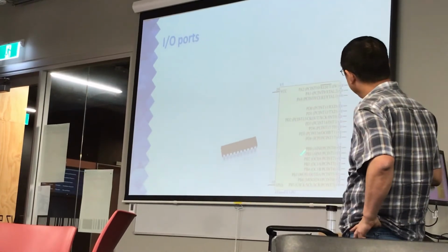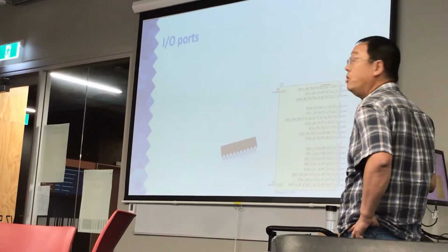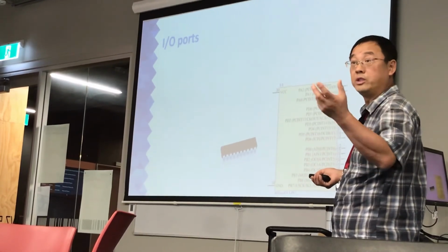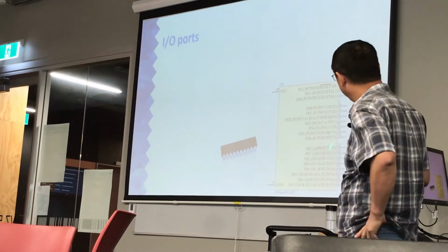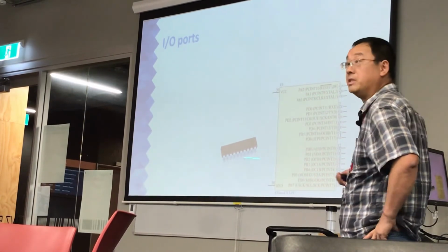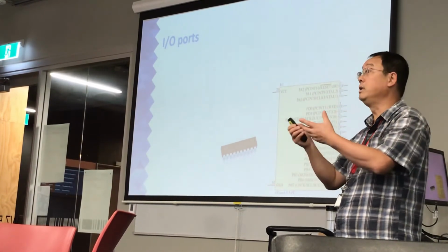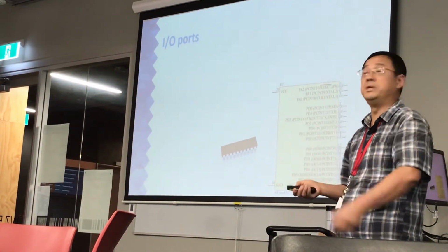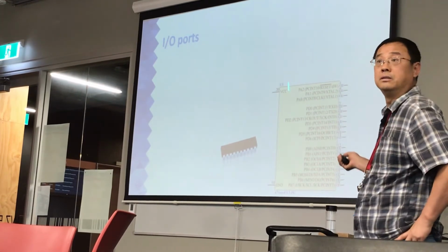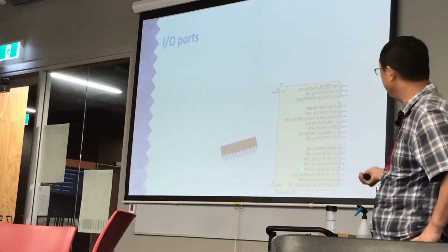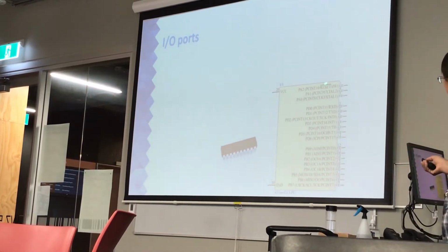For the microcontroller, we can see that one of the microcontrollers is the ATtiny4313, a little bit different from the 2313, which we use on project 2. The reason it's different is they have more I/O pins than the 2313. Because in project 2, we are using few I/O pins. We don't need a complex system. But I just got the electric symbol of the 4313. We can see they have a lot of I/O pins for this microcontroller.